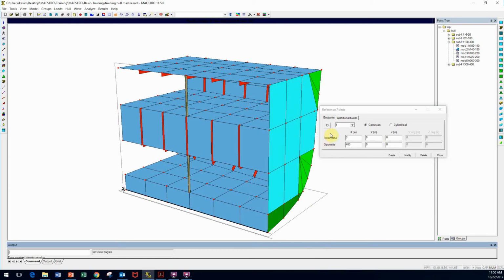Endpoints have a reference end and an opposite end. The reference end is at the beginning of the module. The opposite end is at the far extent of the module. This module has 6 sections with a frame spacing of 80 inches, hence 480 inches for this module, for this endpoint.